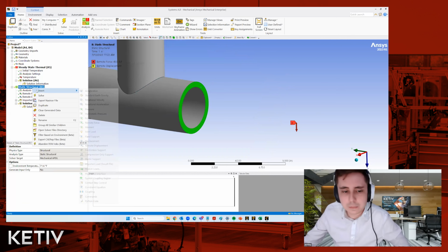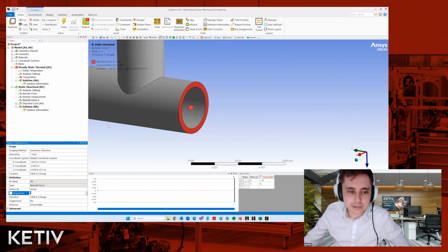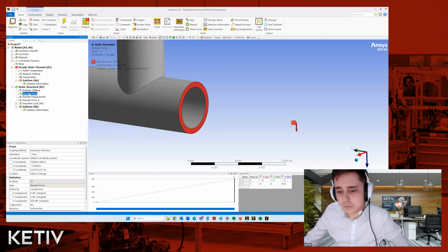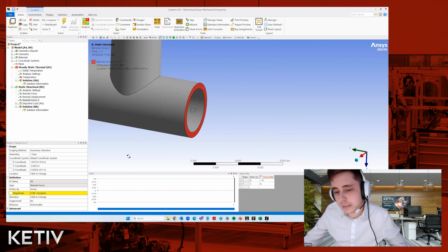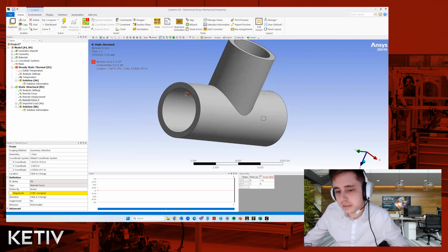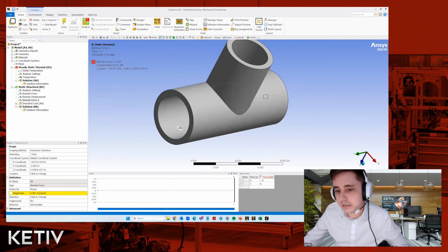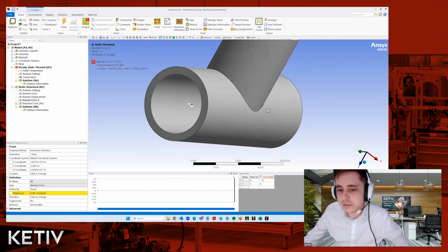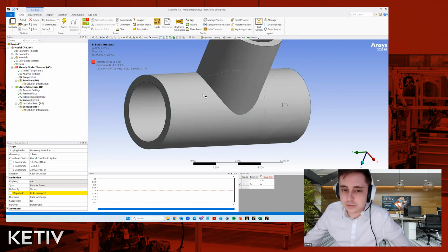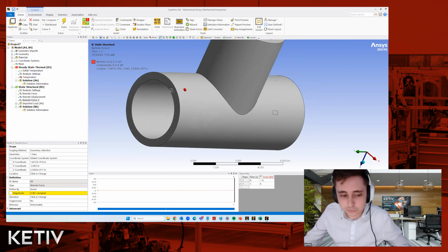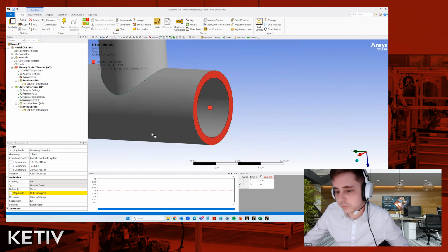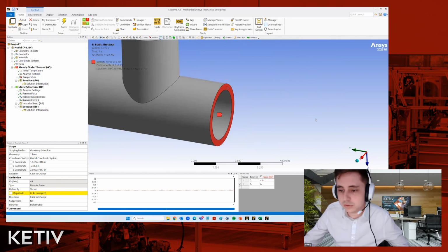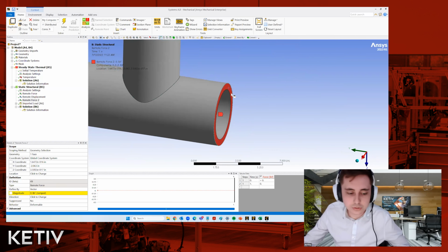We have this tool in Ansys Mechanical called a remote force. You'll notice I had a remote force in here earlier, but what the remote force is, it's very similar to the remote displacement, where you're applying this boundary condition not directly to the nodes themselves, but to some pilot node, and then it's translated to those nodes. So we can apply this force 1 foot away to some pilot node, and it'll transfer that force to those nodes through these constraint equations in a similar way to the remote displacement.